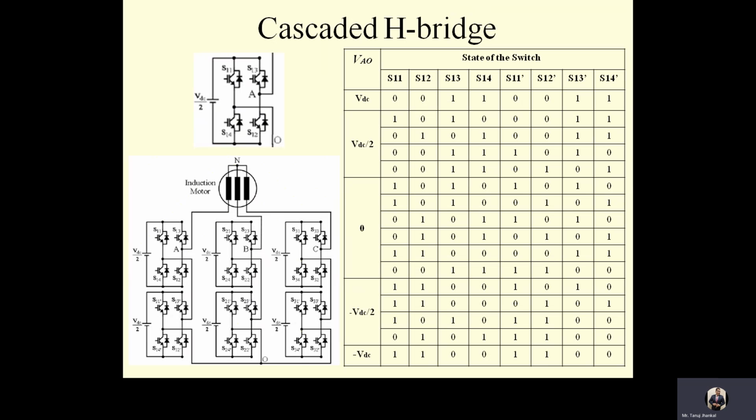For the cascaded inverter, an active front end for regenerative capability is also reported in different literature. The controlled front end rectifiers for individual cells provide regenerative capability to this configuration.